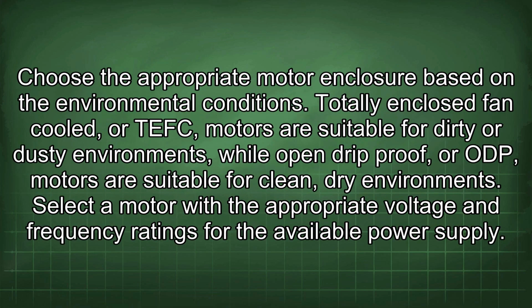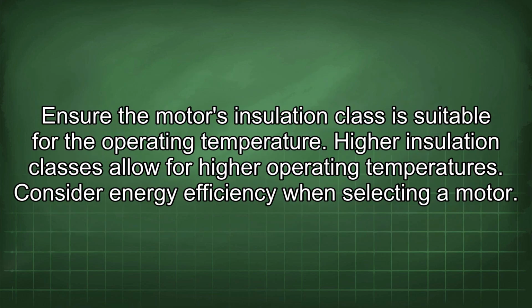Choose the appropriate motor enclosure based on the environmental conditions. Totally enclosed fan-cooled, or TEFC, motors are suitable for dirty or dusty environments, while open drip-proof, or ODP, motors are suitable for clean, dry environments. Select a motor with the appropriate voltage and frequency ratings for the available power supply. Ensure the motor's insulation class is suitable for the operating temperature. Higher insulation classes allow for higher operating temperatures.